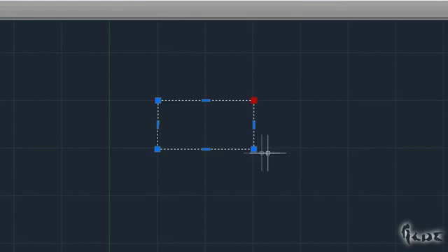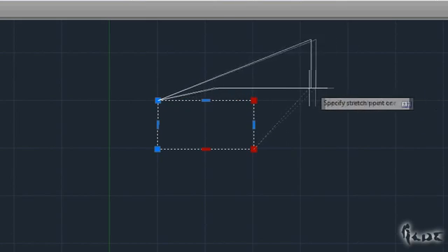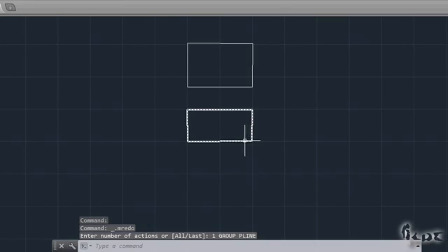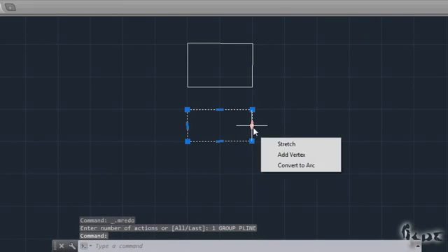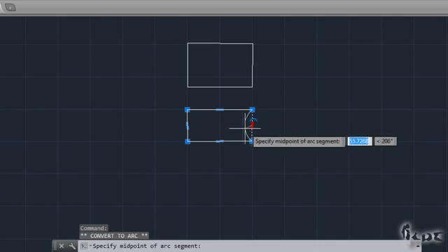Hold Shift down to select more than one point, to keep constant the sides that are between such points while editing. To make one of the straight lines curved, just hover for some time on the small rectangles until a list shows up. Go to Convert to Arc to start editing.